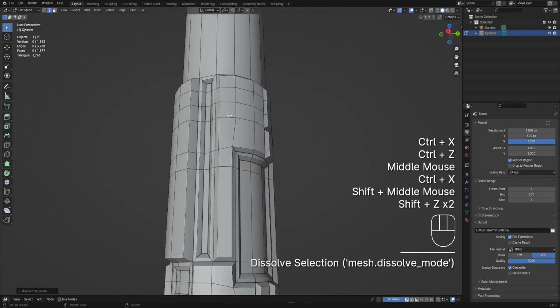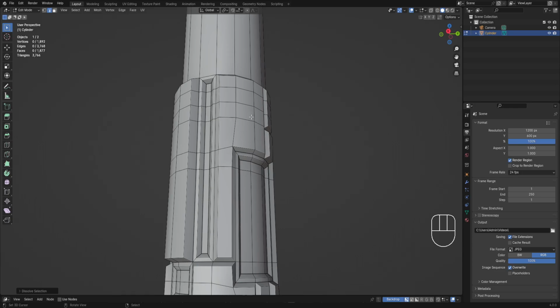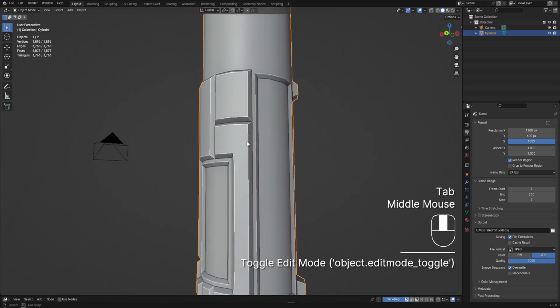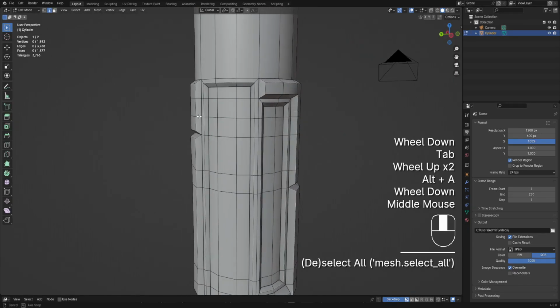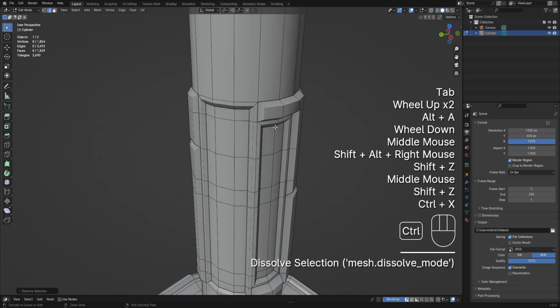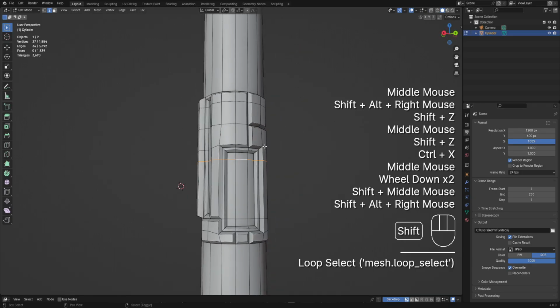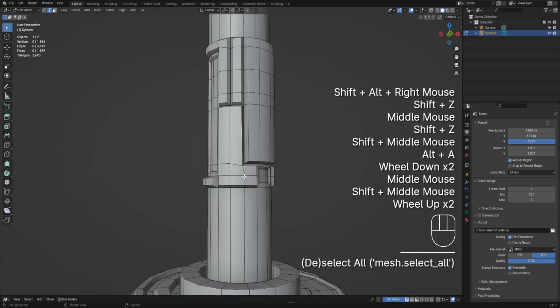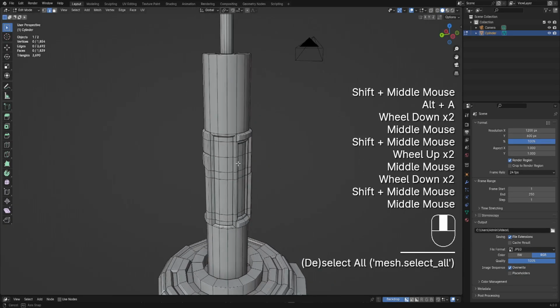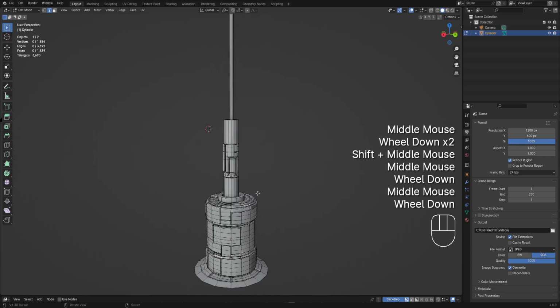So not only would you look for any geometric distortions when trying to prepare the topology like this, you also need to look around for shading errors because sometimes when removing faces, you can have shading errors. Okay, we need this one. And we also need this one. Yeah, I think we're good.